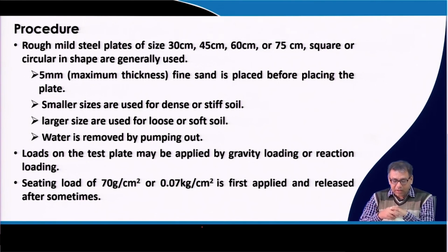When you do the plate test, before you place the plate on the foundation bed or the soil, you place a 5 millimeter thick sand pad, then you place the plate. The smaller size plates are used for dense or stiff soil, and the larger size is used for loose and soft soil. If there is water within your test pit, you pump the water and remove it from the pit, and the loads are given by the reaction frame.